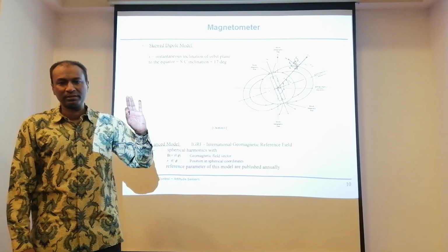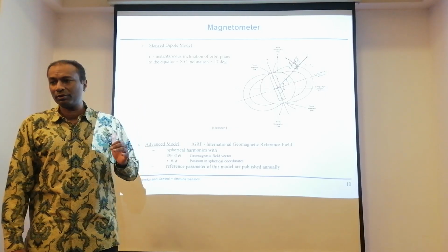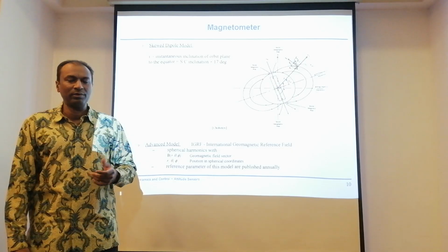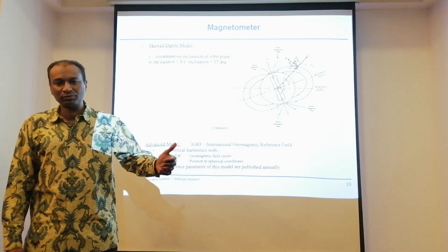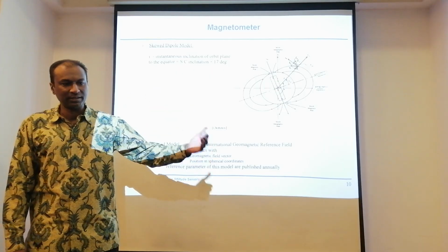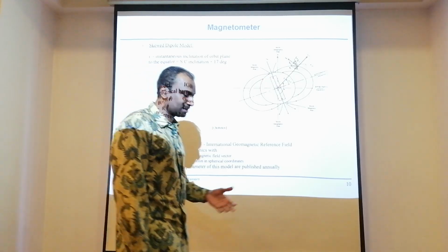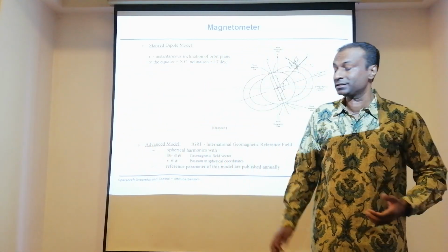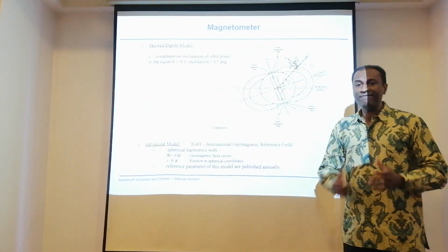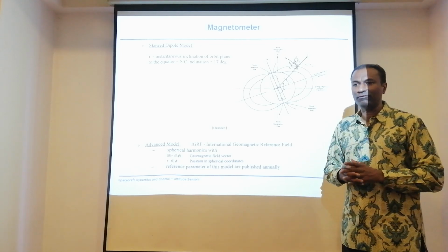Now, just remember, if you want to do attitude determination estimation, the IGRF model is what is desired. You can't get away with a simple model. But for attitude actuation, prediction, and the disturbance calculation, you can use a simple model, because what matters is the maximum disturbance, or the worst case. In this case, every single moment we need to know how this magnetic model is evolving. Okay.